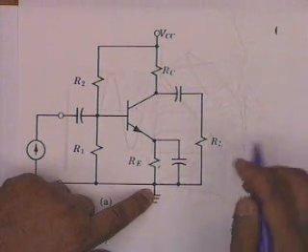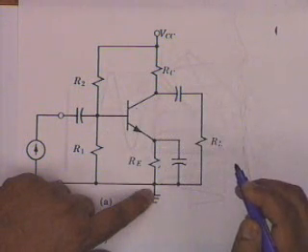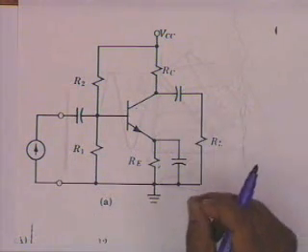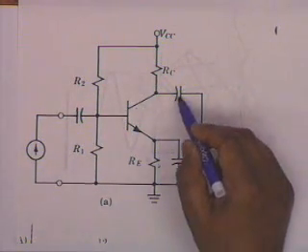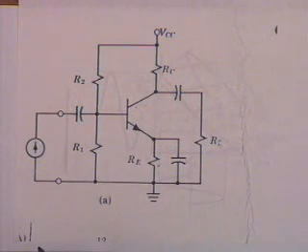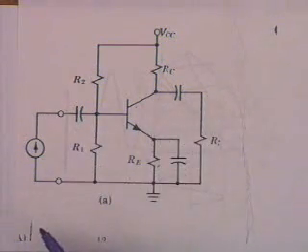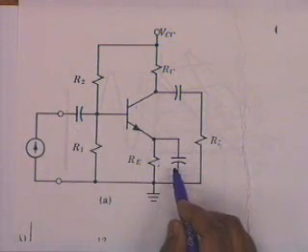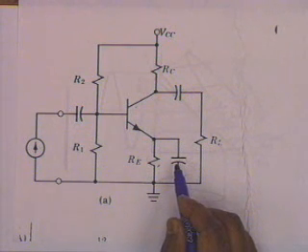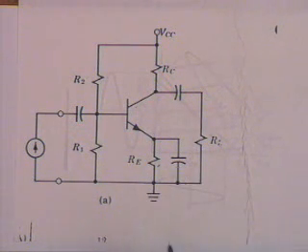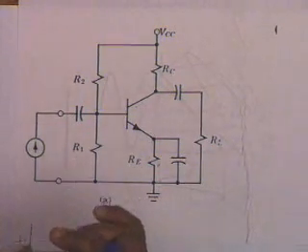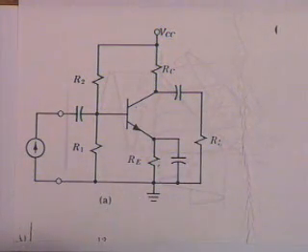Is that okay? The three capacitors, do you understand this? Pardon me? Blocking capacitor is this one and this one. Okay, they block DC. But this is called a bypass capacitor. All right? Okay. Now you should understand, it also creates complication now. It creates complication. It's not as simple as we have presented here.